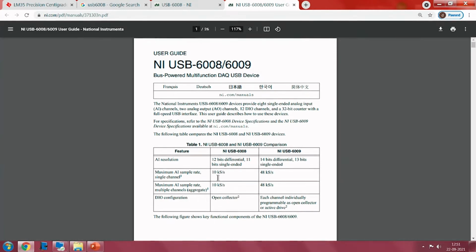But to replicate multiple features, in general cases we use 5 to 10 times. Considering the factor as 10 times, 10 kilo samples divided by 10, it can measure up to 1 kilohertz of frequency. If we use a lower factor, say 5, it can go up to 2 kilohertz as input signal too.